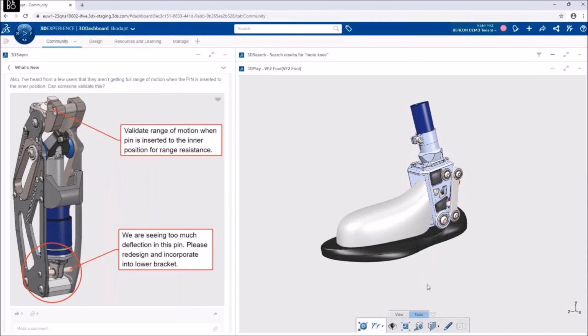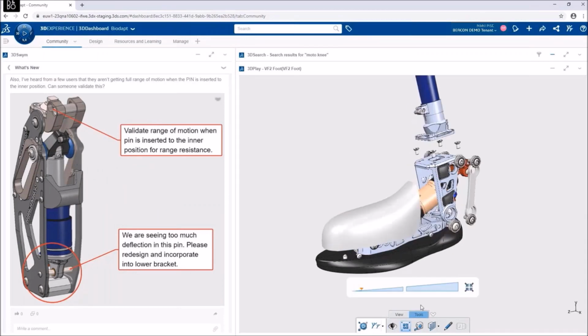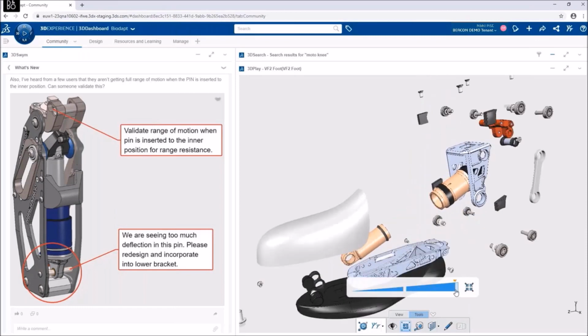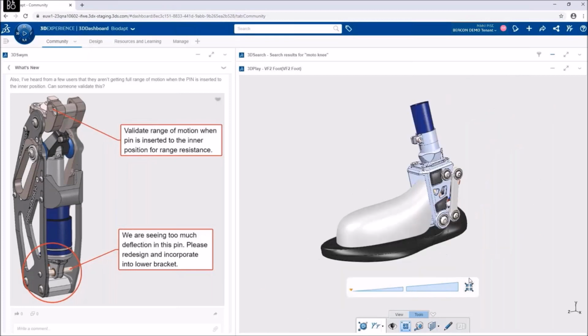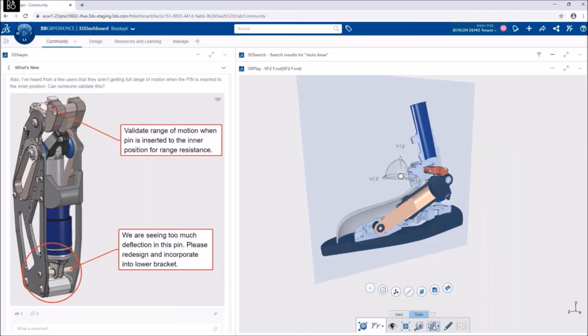It's very easy to use. Like you can just hide and show some components which are required, and then you can create an exploded view. Then we can take a section. So to check the assembly's internal components, you can quickly check it with the help of various planes.